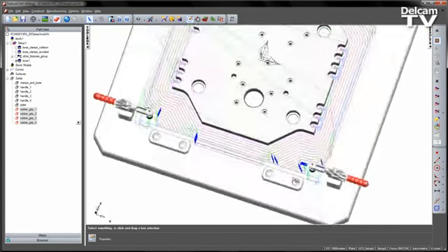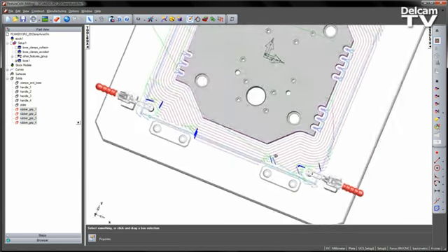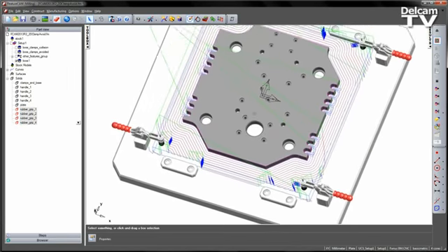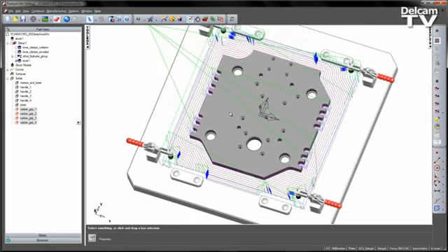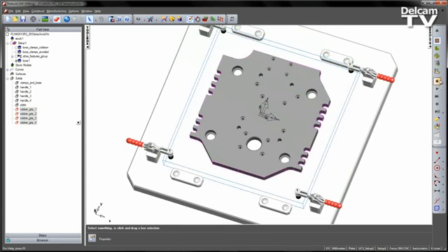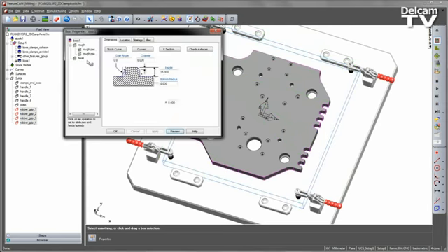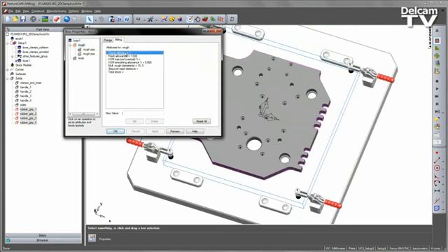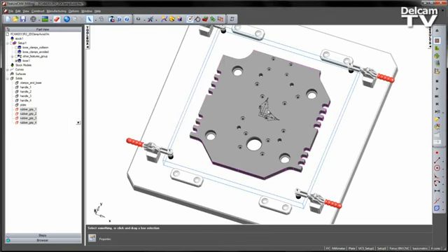However, all that's doing is simply trimming to the exact boundary around the shape of that clamp component. So I also want to provide a check allowance to make sure I'm safe of my surfaces. So again, to do this I'm just going to go into my rough operation. There's no check allowance set, so I'm going to put in a check allowance. In this case I'll set this to be 10mm. Let's do a centerline simulation.